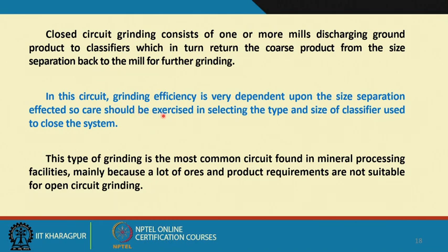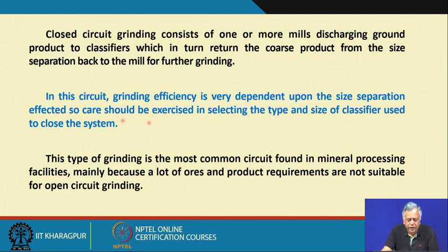In this circuit, grinding efficiency is very much dependent upon the size separation effected. So, care should be exercised in selecting the type and size of classifier used to close the system. That is why the selection of an appropriate cyclone design is important.